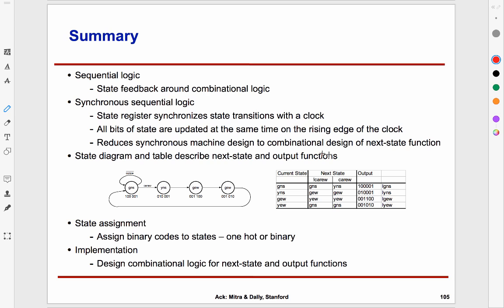And I see questions like, can I use splitters? Of course you can, because they're just wires. They just make drawing easier. Likewise, can I use an n-bit AND gate? Sure you can. It's just a compact way of drawing things. A k-input AND gate ANDs k things. An n-bit 2-input AND gate really says I have n AND gates of 2 inputs each, stacked in parallel. As long as you count the cost correctly, it's nothing but a compact way of drawing.